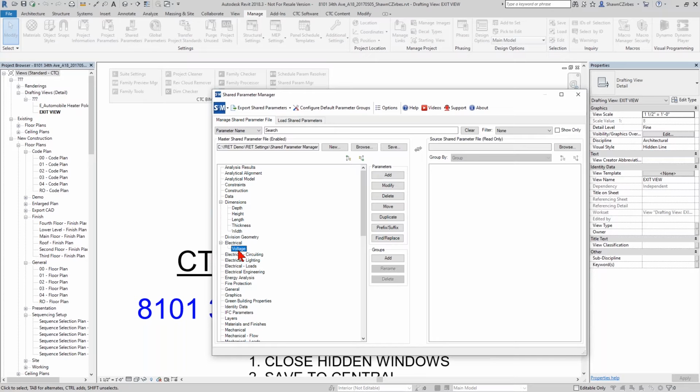So you can think of a shared parameter like a recipe in a recipe book. You can think of a shared parameter file like the actual book or box the recipes are stored in, right? When you're using that parameter in the first place to create the parameter definition in a family or a schedule or something like that, you only need that recipe while you're making it. Later, if this entire file gets deleted, you know what? It is what it is. It's deleted, but that component that was made has already been made. It doesn't need the recipe after that creation point.